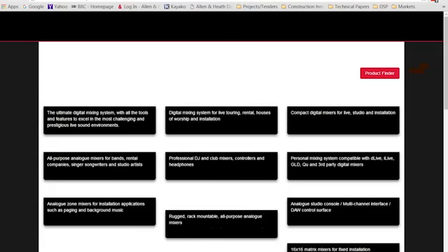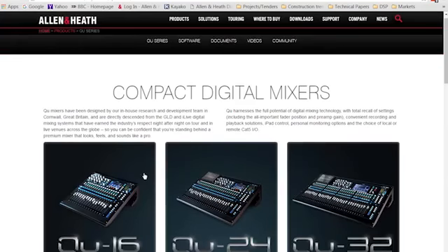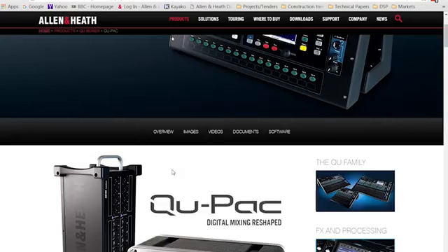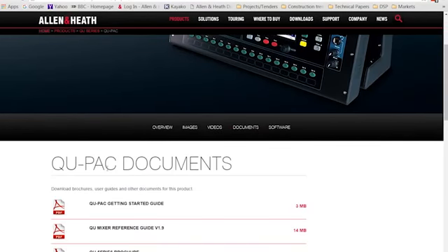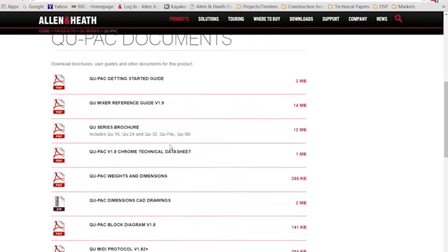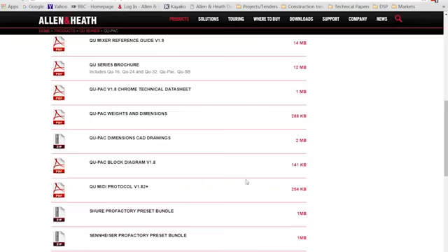Yeah, thanks. So please, guys, do send in any question you might have. We have just a few at the moment. One of these is about something you mentioned earlier on about the extra latency when you use a switch to connect DLive products, for example, a stage box and a surface. Now, we said DSnake has about 100 microseconds of latency. The extra latency that a switch would add, we have done some calculations with some of our products, and I would say it's negligible. So we're talking nanoseconds, which in a typical audio application is really not critical.